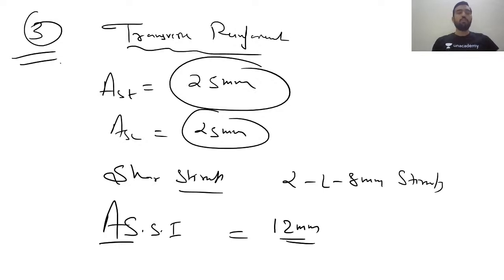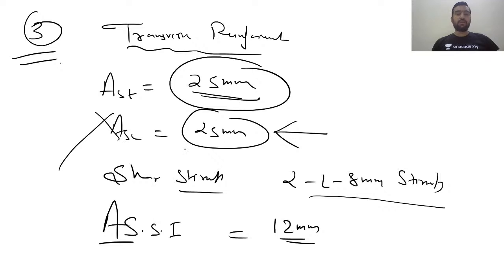Okay, so you are going to tell me the spacing of shear by using 2 legged 8 mm stirrups. Compression steel is not required from design point of view, but from the connection point of view we are going to give it here. AST we have already calculated. Now guys, day after tomorrow you have to tell me the spacing as well as the number of bars of side face reinforcement, and you have to check whether side face reinforcement is really required or not, isn't it?